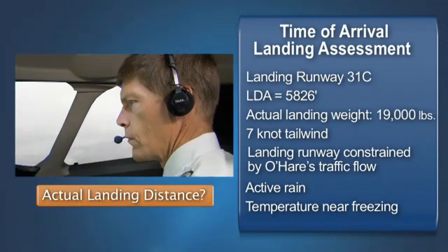Based on the ATIS information received, what would you consider when performing a landing distance assessment? At a minimum, we should consider the operational impacts of the wet runway and the tailwind.